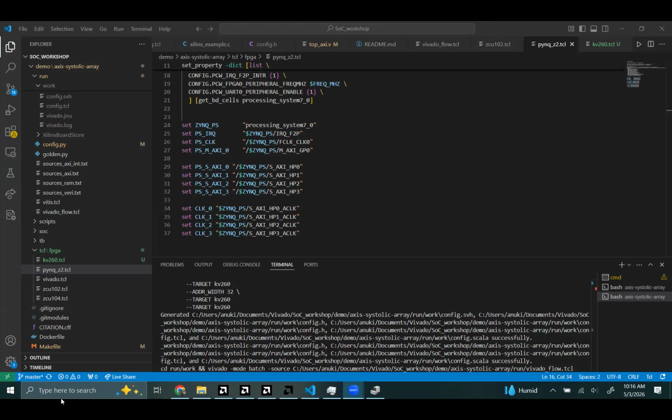I tried it, and the thing is that the Vivado block diagram has some problems, in the sense that there are very specific requirements on what the top module should look like. You should not use SystemVerilog; you have to use Verilog. Because of that, you might have some issues when copying stuff. But as I said, you can just put everything together in your own Verilog file and introduce that to the block diagram. Okay.